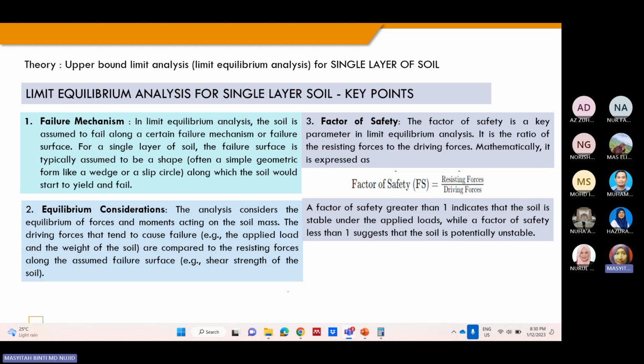So the factor of safety, kalau tengok kat sini is in the definitions just now. Factor of safety kalau ikut application selalunya berbeza lah. For example, kalau kita analyse for the bearing capacity, most of the time kita can choose the factor of safety around 2.5 to 3.0. If you have another kind of geotechnical application, contohnya slope stability, so kita boleh letak dia sebagai 1. So if you have FOS more than 1, we can consider that our calculation or the structure is safe. Tapi kalau kata you calculate FOS tak dapat lagi 1, maknanya you have to recalculate until you can get the right one.